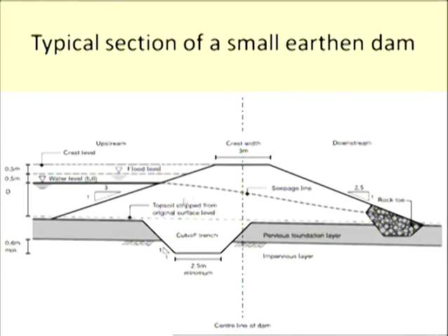And the top line, here you look at the seepage line, is sometimes called the phreatic line, the top seepage line or phreatic line. And this is the water level, a flooding water level, and in no case should this earthen dam be overtopped, in no case, because if any portion of this earthen dam is overtopped with water, then there is no possibility of it standing in position.